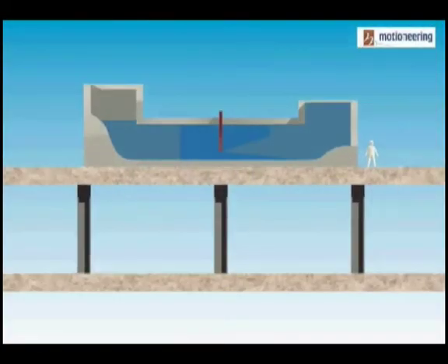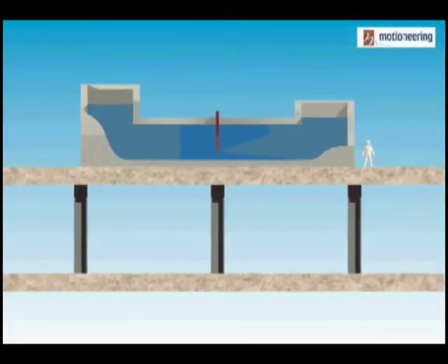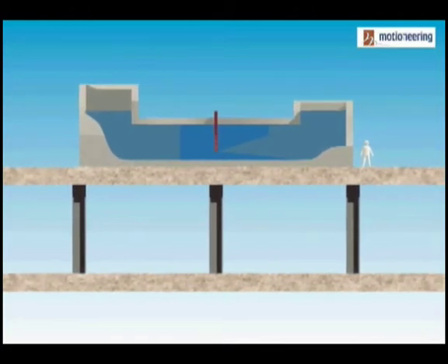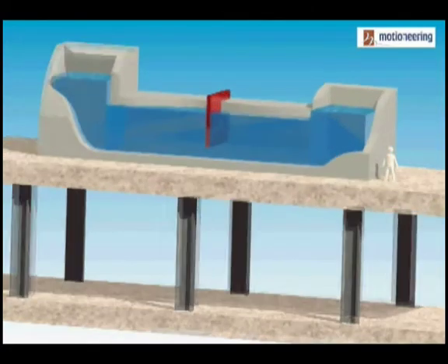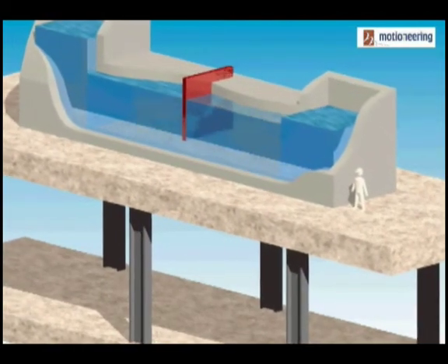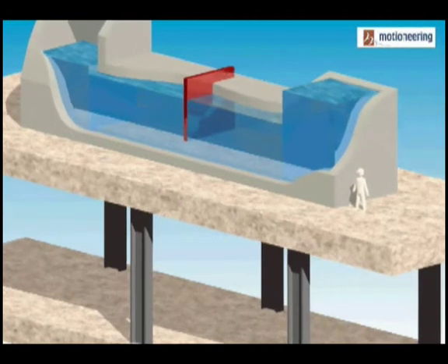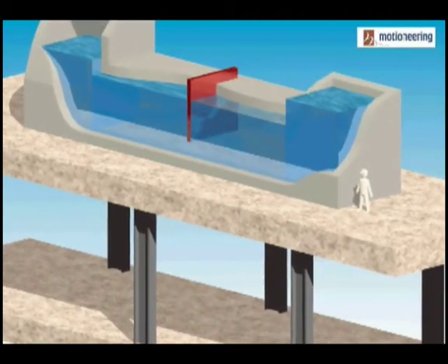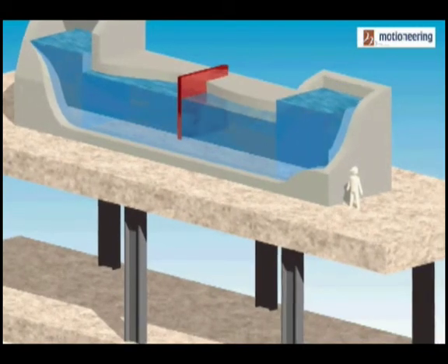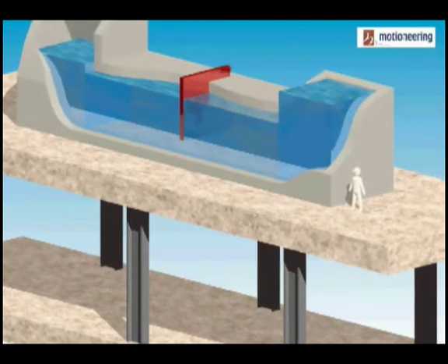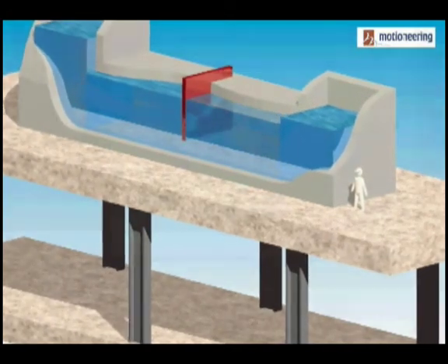This is an example of a liquid column damper again. Wind can be a foe, but we can make friends, if you like, and we can use some fairly economical ways of doing that, using existing water storage tanks on the top of these high-rise buildings. They can be tuned to the same periods of vibration of the building and reduce the fluctuating motions of the building.